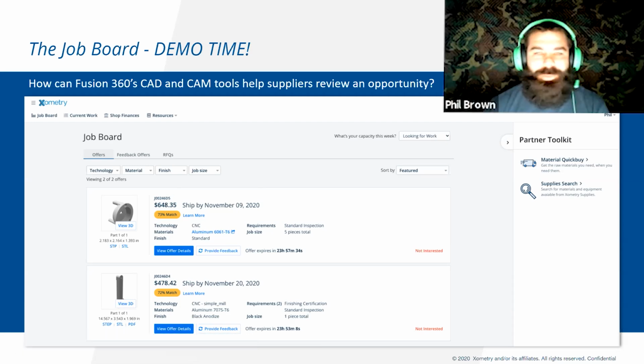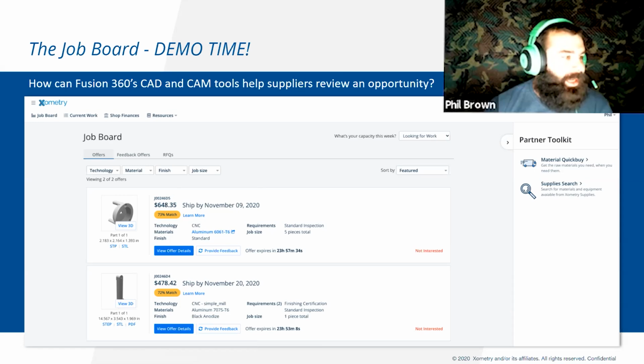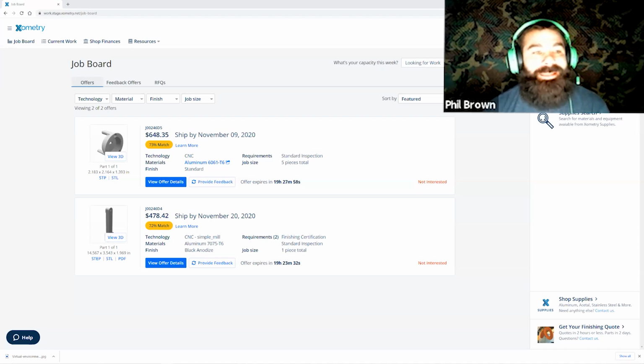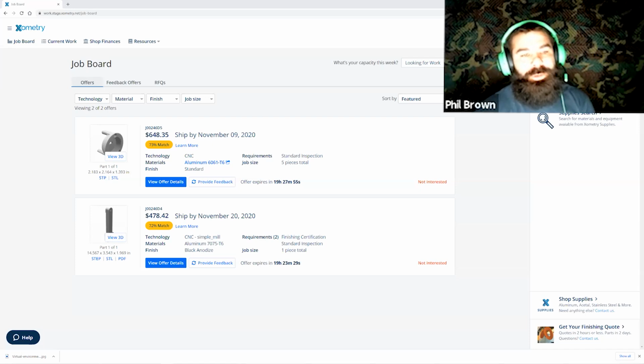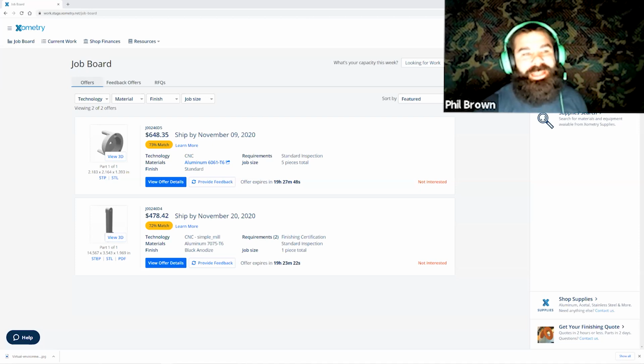Yeah, no problem. So we did have another question come through that was a pretty good question, and I actually know kind of the answer to this myself. Somebody's question is, in the event that they have used Xometry for quoting, the price for finishing, such as anodizing, has been substantially different. Being somebody that has manufactured parts and sent them out for coatings, I will tell you, an anodizer that I worked with charged $175 for the tank. Whatever fits in the tank, it's still $175. If I had 100 parts or one part, it's still $175.